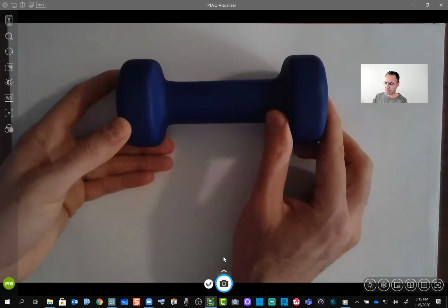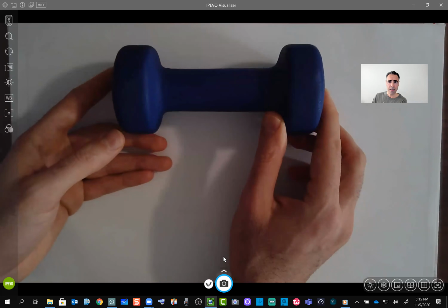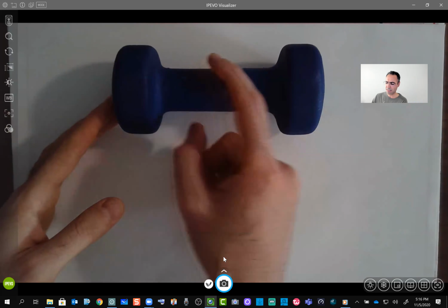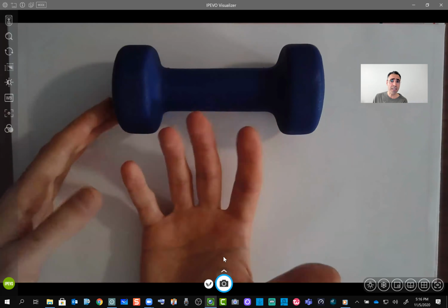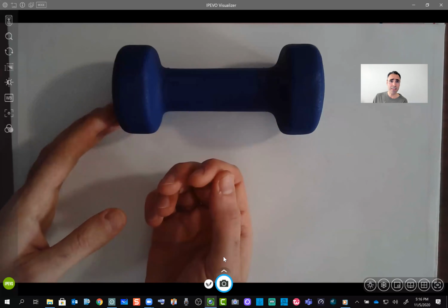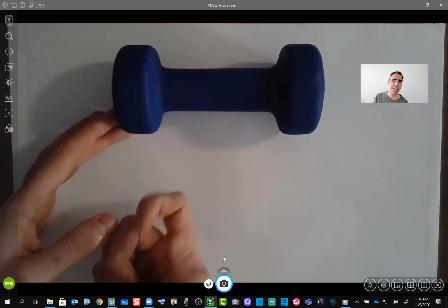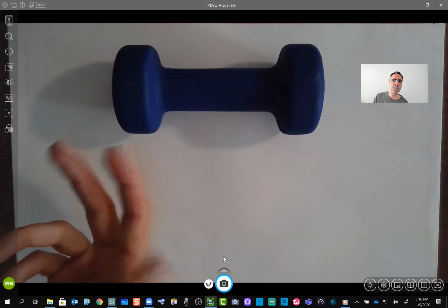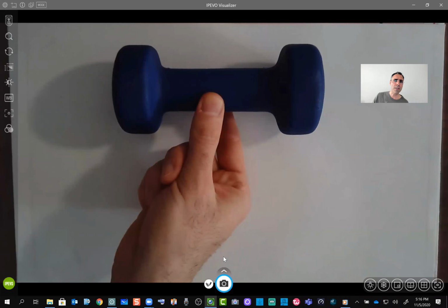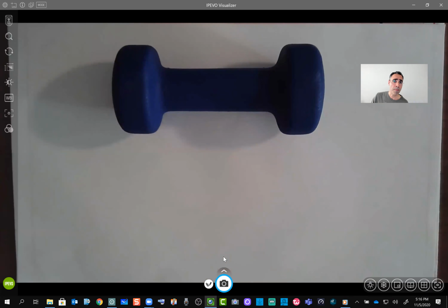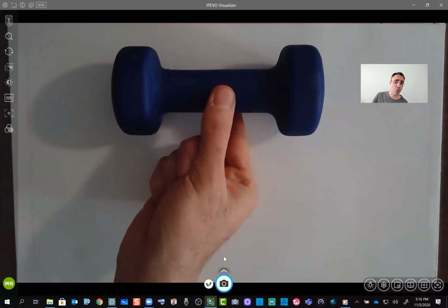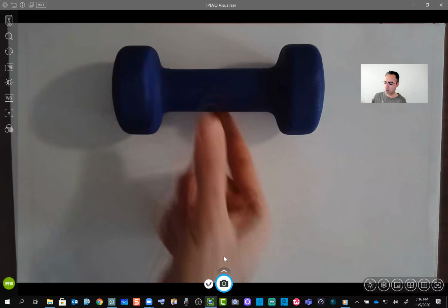Casting these things is going to have one issue. Typically in casting, we are not happy if the thickness is big, because then the solidification is going to take time. And time in manufacturing is a big factor because it basically increases the cost, and we are not happy about that. You can imagine a thing like a dumbbell sells for only a few dollars. You don't want to wait, let's say, 10 or 15 minutes just to make one dumbbell. So casting is maybe not a good way.